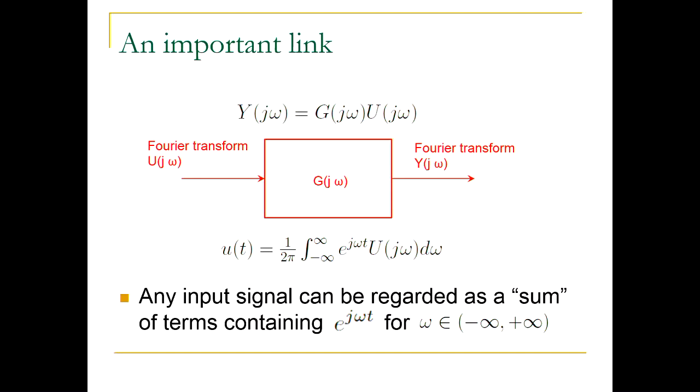So this gives you a very nice interpretation of what's happening in the linear case, because the steady state response due to a signal that is a sum of sinusoids is the sum of steady state responses to each individual sinusoid. This is because of linearity. So we would use the superposition principle to conclude something like this.